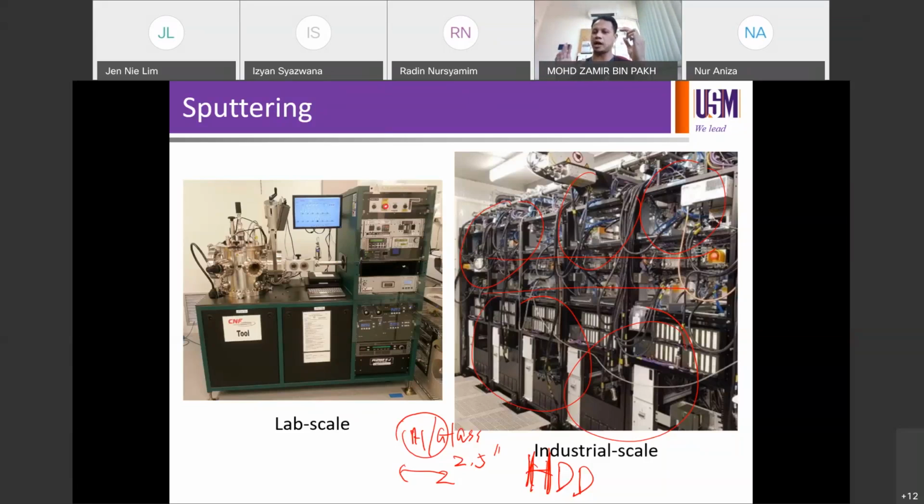The main processes are just in the sputtering. So you can have your glass disc or aluminium disc with the layers just by sputtering process alone. There's no lithography, there's no implantation, there's no diffusion, nothing else. Just glass cleaning in the earlier part of the process flow, and then you're gonna have like sputtering,